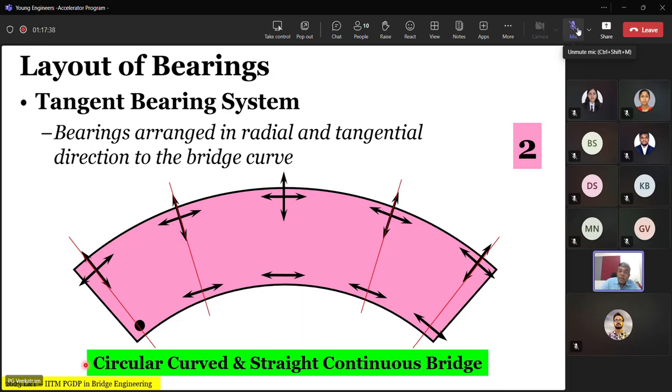So either way, in whatever choice you make, if you choose polar radiating, then you will get transverse direction forces under the pre-stressing and creep behavior. If you choose tangential bearing system, you will get transverse resultant forces under gravity loads as well as under temperature and thermal stresses. So there is no situation in any articulation that you can actually avoid stresses, because we have a mixture of loading. The main problem is we have a mixture of loading on all bridge decks.